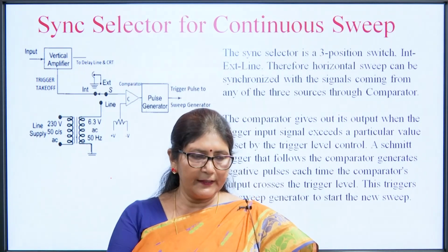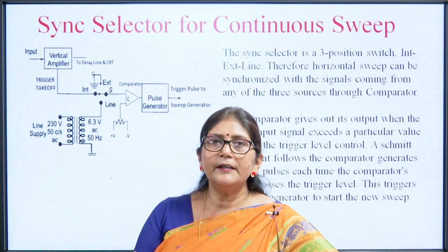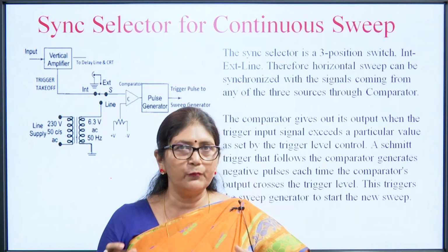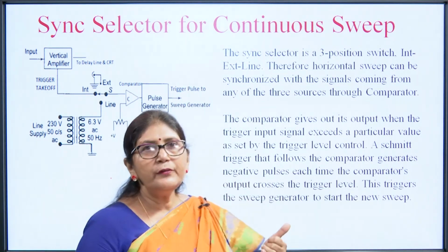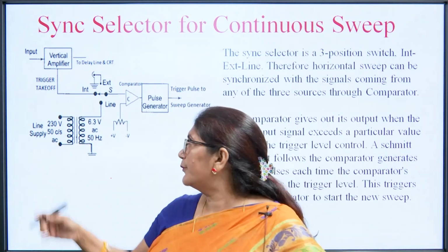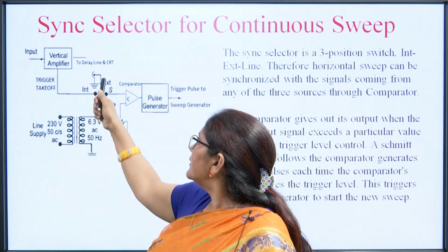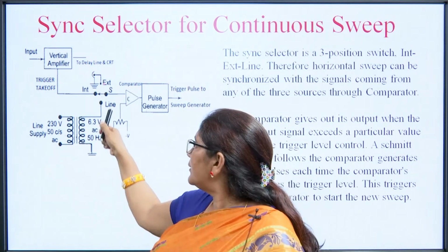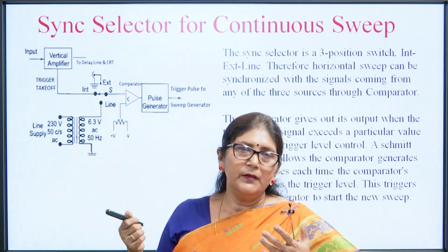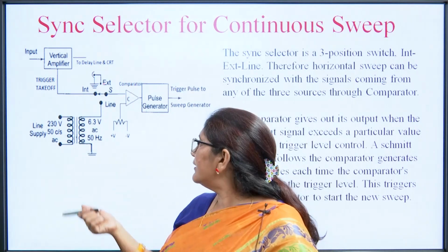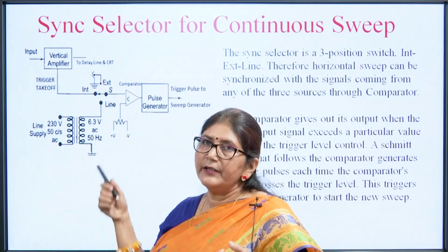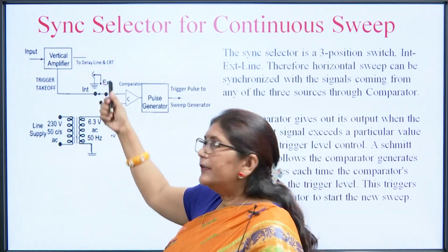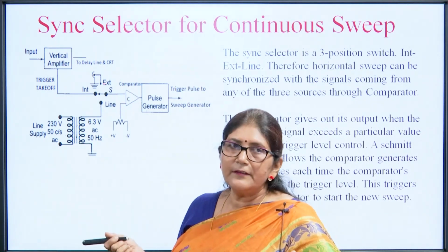Now, the sync selector circuit. In the sync selector circuit, there are three modes: external mode, internal mode and line mode. For line mode, we directly provide the main line frequency, that is 50 hertz frequency. So, we can connect it to this terminal. In external mode, we can connect it with any external signal.